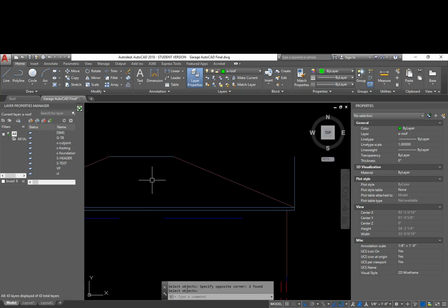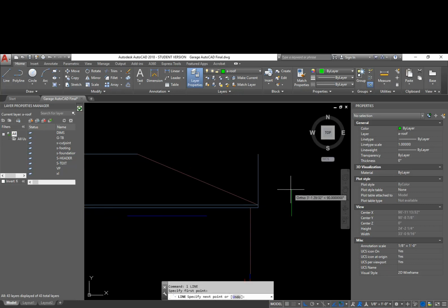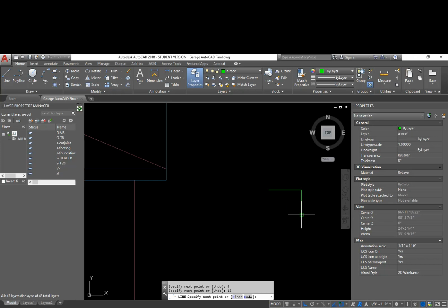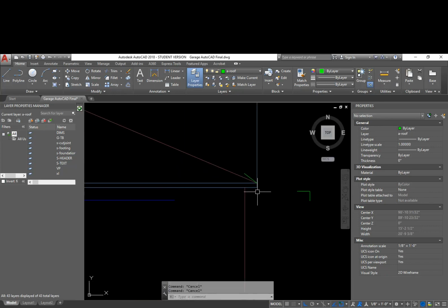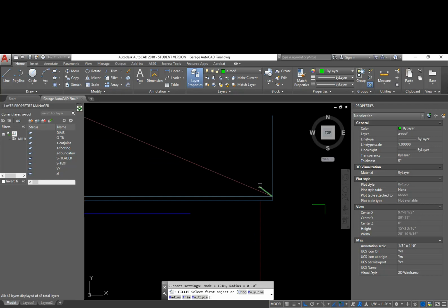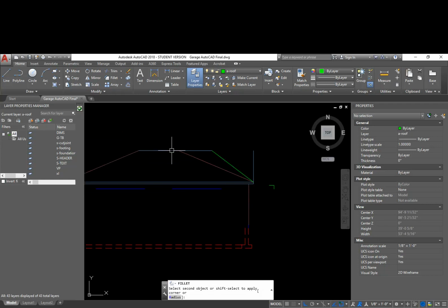of the roof sloping at 5/12, but this part, the two end hips, sloping at 9/12, I would just simply have a line that represents the 9/12 roof pitch. So I just drew a vertical line 9, horizontal line 12. I would move this into place, and I could fillet this and that.